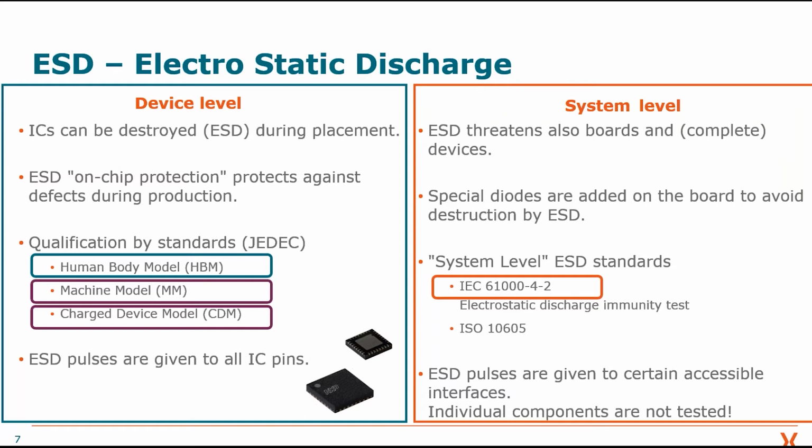But then there's a system level view, and this is a completely different view. You do not look at every device, but you look at the total electronic modules. For example, an automotive cluster or display module, or mobile phone, or also a complete PC. So from the perspective of the ESD protection vendor, as Nexperia is, we will look at both, so at the device level, but with a big focus on the system level here.